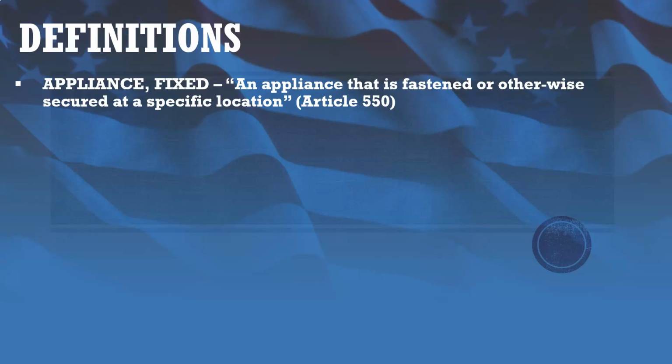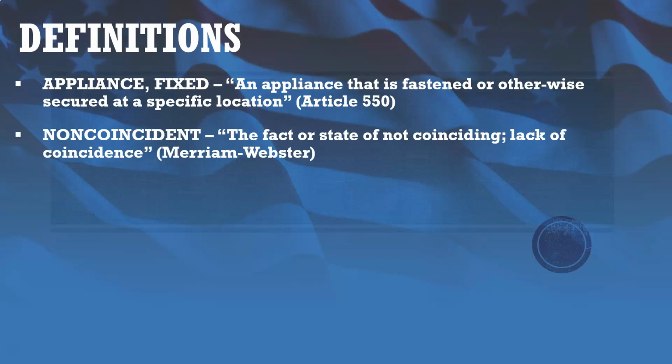Same deal with a refrigerator. On the other hand, if we think about a water heater, it is mechanically connected to the plumbing system via PVC piping usually, and usually it'll be hardwired from a non-fused disconnect using flexible metal conduit or MC cable, something to that effect. So essentially something you need tools in order to remove is how I like to think of a fixed in place appliance.